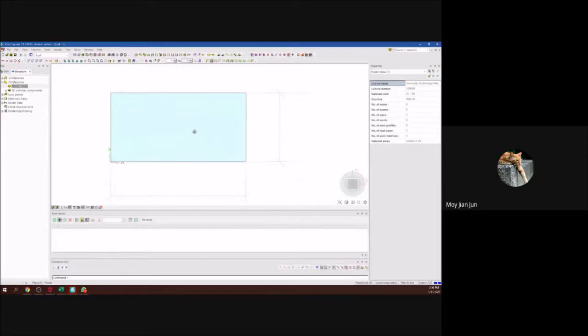Okay, after I have modeled my plate, I will choose the boundary. The support is in the model data tab. So I will press model data and then press support. Our support in example 8.1 is at the line on 2D member edge, so I will press this.